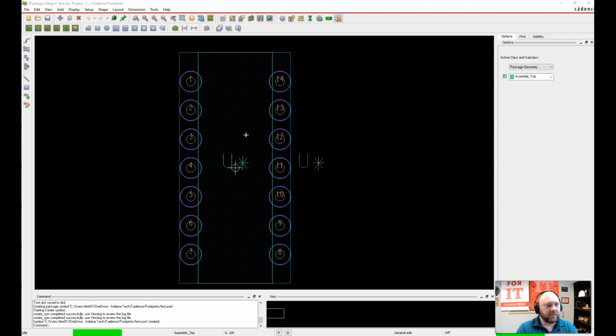And we'll be able to see what all these different colors mean here. One of the things you can see as far as what these different colors mean, if I go here and look at the active subclass, there's all sorts of different, these are all actually different layers, believe it or not. So like there's board geometry, but we're not talking about the board, but package geometry.